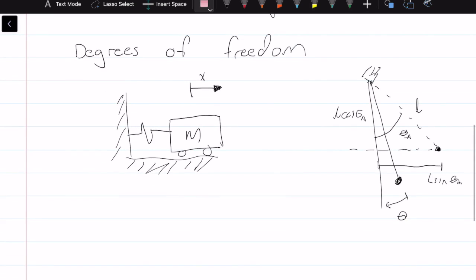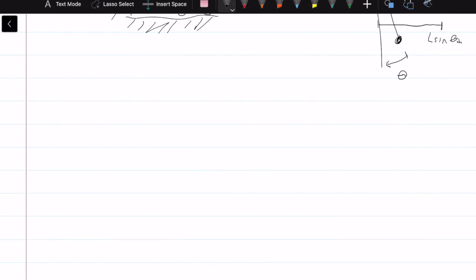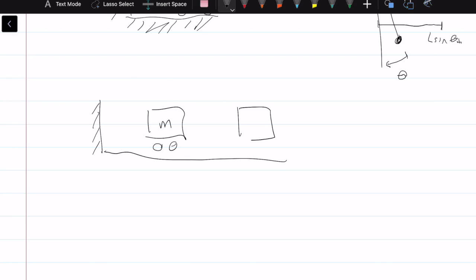But we also can get double or 2 degrees or 3 degrees of freedom, so we need to take those into consideration as well. We won't be dealing with them right now, but an example of one would be the system right here. We've got one mass here and a second mass here, and they are separated by two springs, K1 and K2. These masses do not move the same distance each time, so this would be x1 and this would be x2. If, however, this was a rigid beam or something, then we could define this entire system using x1. But because we've got a spring right here, we need x1 and x2. But for now, like I said, we're going to be dealing with single degrees of freedom for quite a while, so we won't worry about that too much.